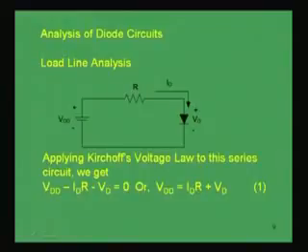That means we will have to draw a load line. This load means the resistance. If we consider only resistance as the component connected in the diode circuit, then the load will be only resistance, and for simplicity we will be considering a resistive circuit, and of course, this is a DC circuit. So, the only component which will matter is resistance.